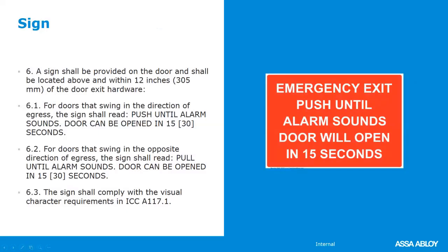And for doors where the delayed egress is on the pull side, "pull until alarm sounds" is what the sign would read. And the sign characteristics need to meet the visual requirements of ICC ANSI A117.1, which is your ADA standard.